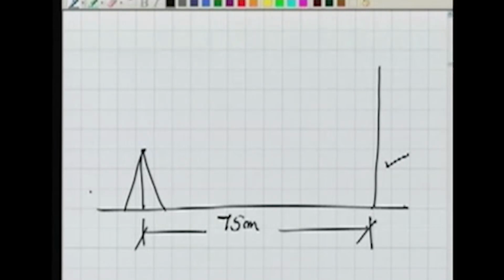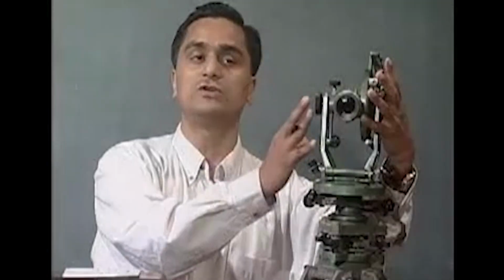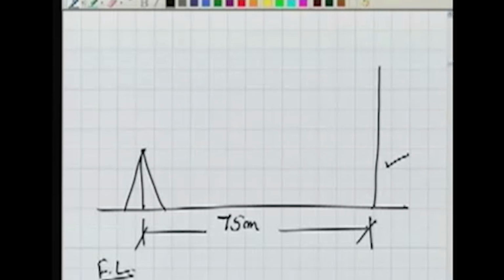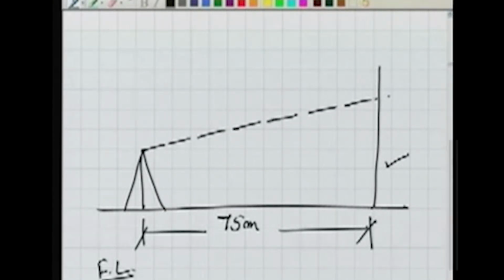Now in our theodolite we keep, let's say, face left, as the face in the theodolite for me is left now. Then we set our theodolite to any particular angle value. Let's say I set my theodolite to 0, 0, 0. How do we do it? We'll rotate it till the readings over here in these two verniers C and D are 0, 0, 0. Well, the readings are 0, 0, 0 now. Then I bisect the ranging rod. So the ranging rod is bisected here at A.